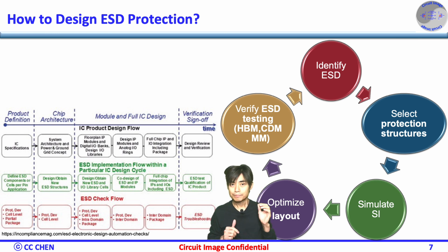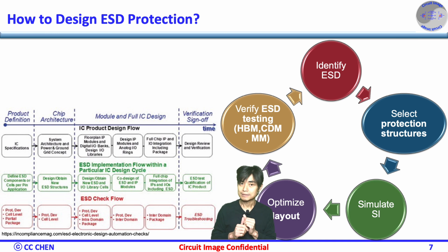HBM mimics a person touching the device. MM represents ESD from handling machinery. CDM replicates charge accumulated on the device itself. These tests involve controlled voltage pulses applied to the IC. Engineers measure if the device survives without degradation.